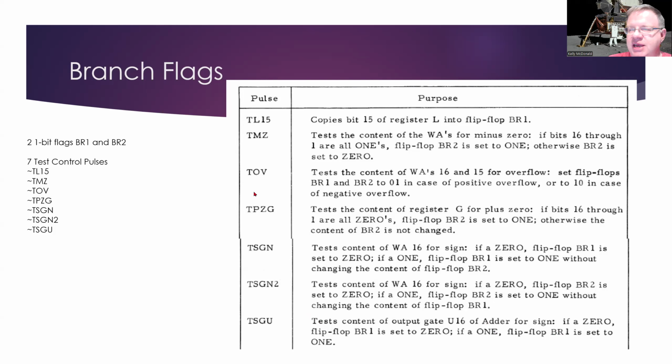Like if you compare this to say the 6502 processor, the 6502 has several status flags that the CPU uses for branching. So based on whatever the last operation was that was done by the ALU, the 6502 will set different flags: if the number is negative, if the number is 0, if we had an overflow, if we had a carry in the last operation.